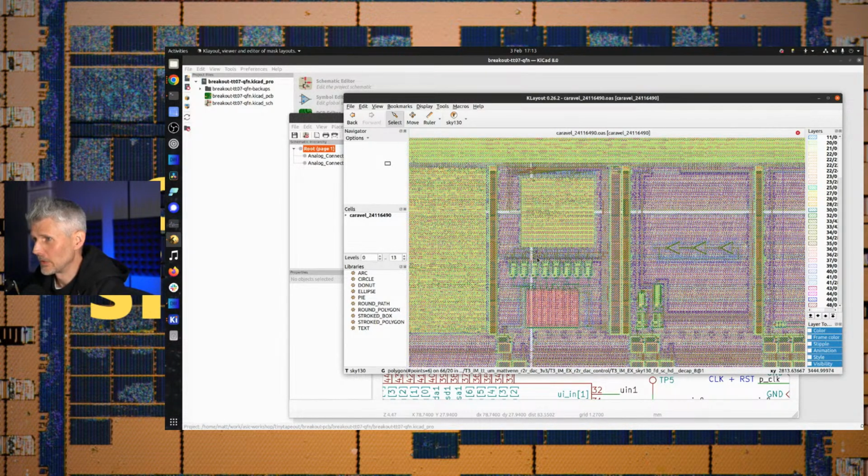So the aim for today is to make a very, very simple digital block, even smaller than this one probably, connect it up to the 3.3 volt rail, and then its IOs are going to go through the analog IOs, because those ones don't go through the digital muxing, because the digital muxing is also going to be affected.